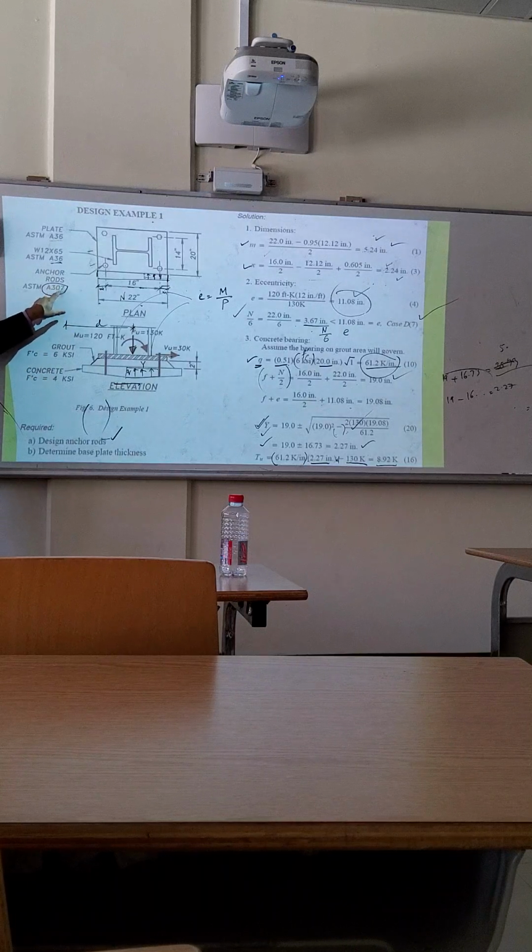So grade is also given. So based on this criteria, you will decide what will be the capacity of your bolt. So you know diameter is required because Fy value will be decided by this. If this is not given, it will be your choice.